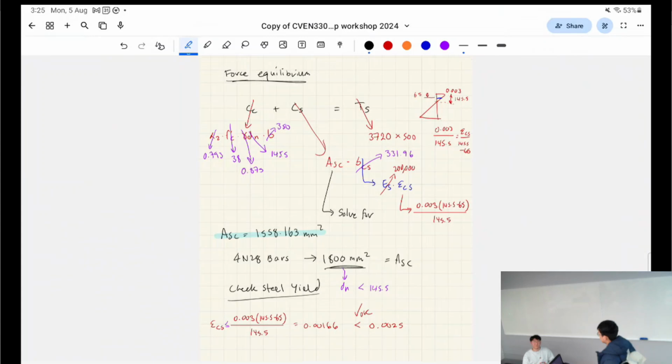which will make it 0.3. Ku of 0.3. Oh, that's fine. Is 0.3 from the standard, like the AS3600 standard? No, that's a designer recommendation. So it will say it in the exam. It'll be like, we want it to 0.3, or sometimes it'll say 0.25. So there's no formula for it because so many things just depend.